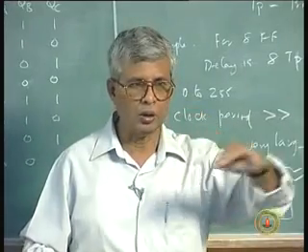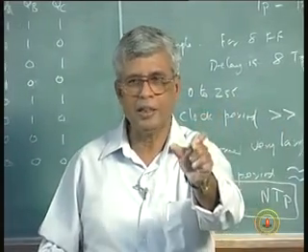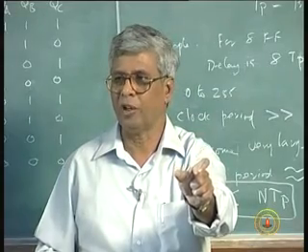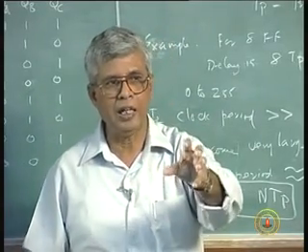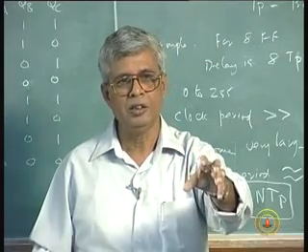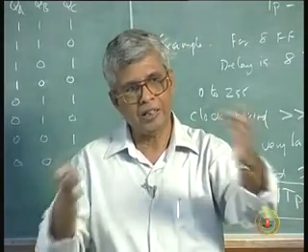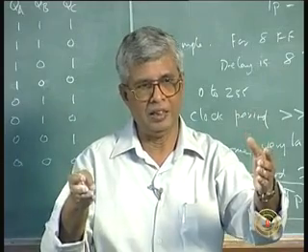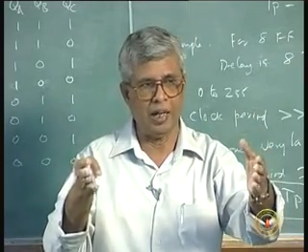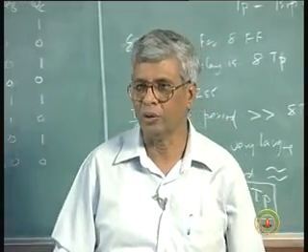It has to go into this, into this, into this, into this. And at each stage it accumulates a delay because of the propagation delay of the flip-flop. So the clock accumulates delay, and if the number of stages is very large, the propagation delay is longer than the time difference between two events, then you lose track of the count.